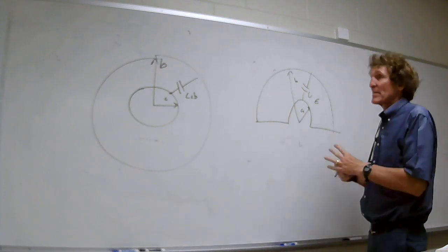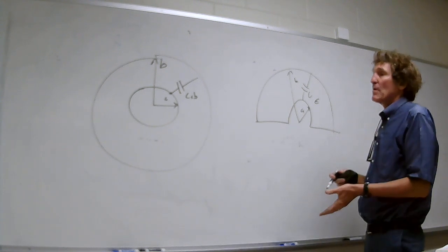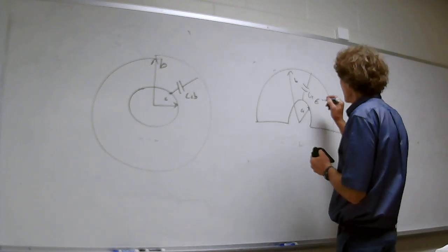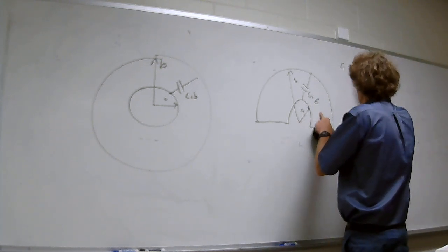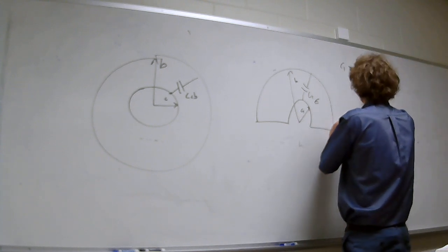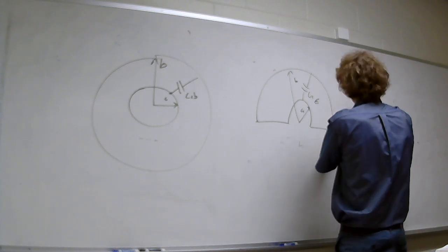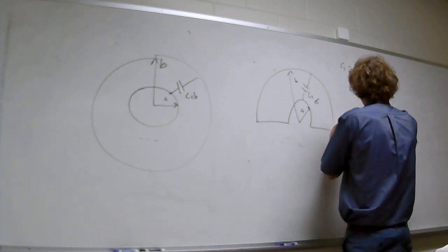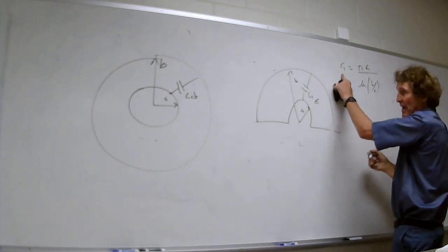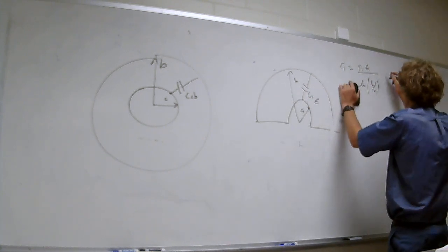So it's like having the thing filled with epsilon 1 divided by 2. So this capacitance, which I've just called C1 here, will be equal to that capacitance divided by 2. It's going to be pi epsilon 1 over the natural log of B over A, because that's half. It's dividing that capacitance over there by 2.